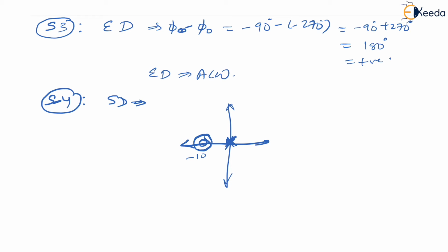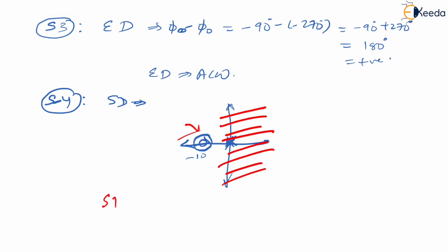Is that right? Yes. Now our thing is that we ignore everything that is there on imaginary axis and on the right half, right? So if I ignore this, what do I observe? I observe that I have 0 first, 0 closer to origin, which means starting direction is again anti-clockwise. Is that correct? So you get ending direction to be anti-clockwise and starting direction to be anti-clockwise.